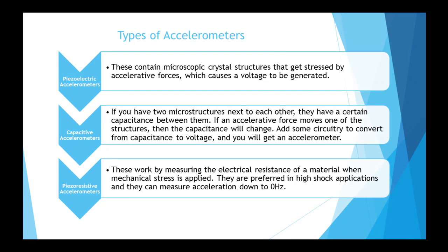Piezoresistive accelerometers. These work by measuring the electrical resistance of a material when mechanical stress is applied. They are preferred in high shock applications and they can measure acceleration down to 0 Hz.